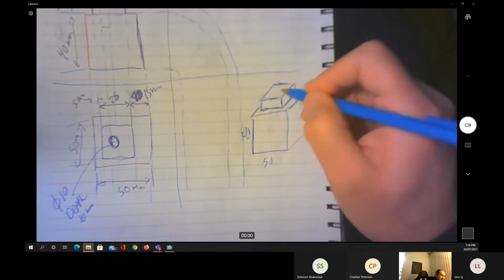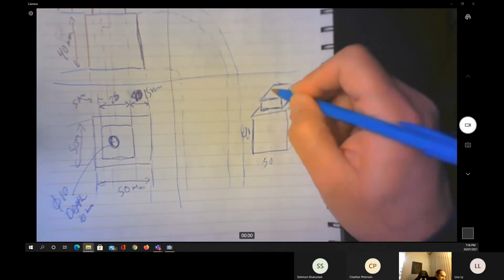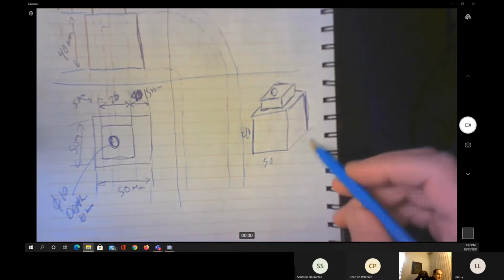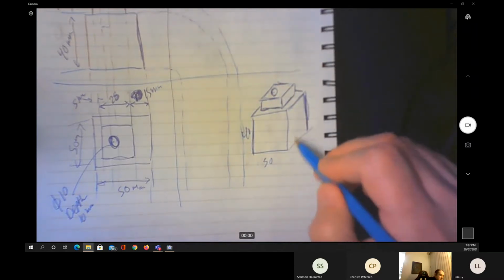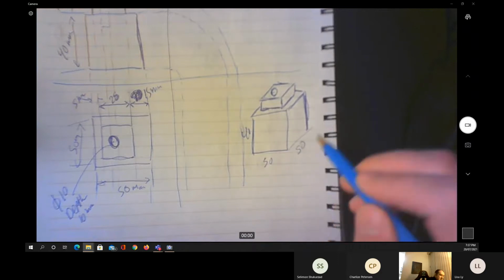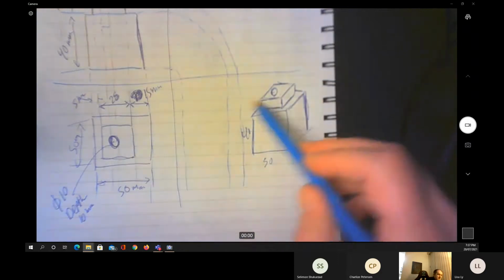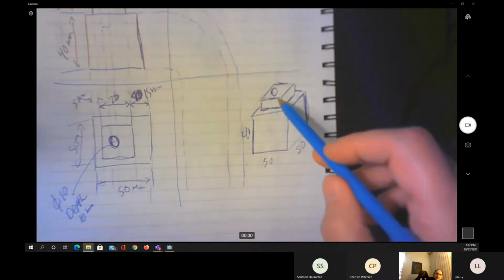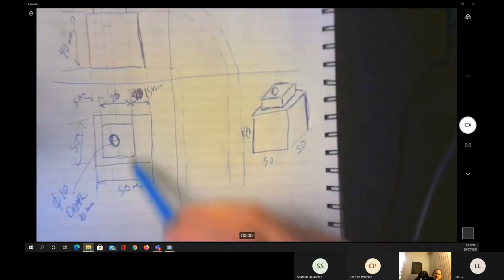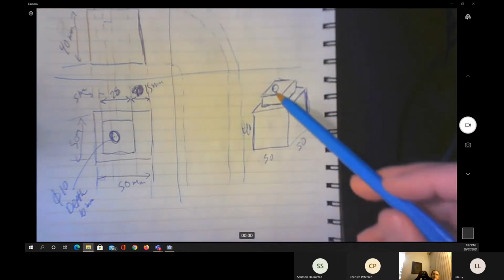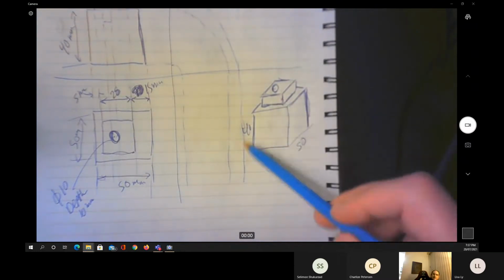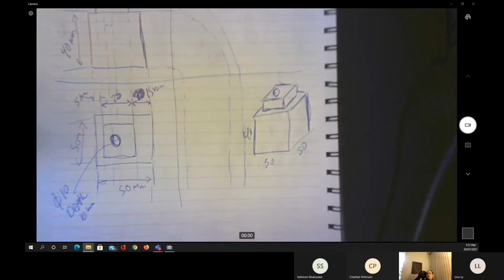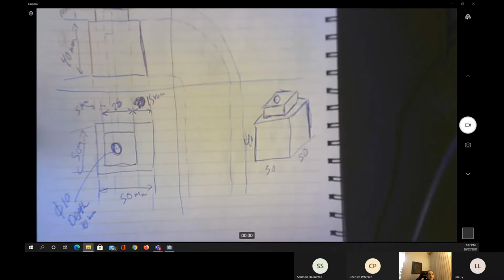And we have the hole at the top here. 50, 40, 40, okay, this 50 of course. And the dimension here is going to be similar to this one, 25 by 25 for the square at the top, and the diameter of this hole is 10. And the height of this block is 10 plus 40, which is 50. So we're going to start with the 50 millimeter block, remove the material just to have this square at the top with the hole in the middle.